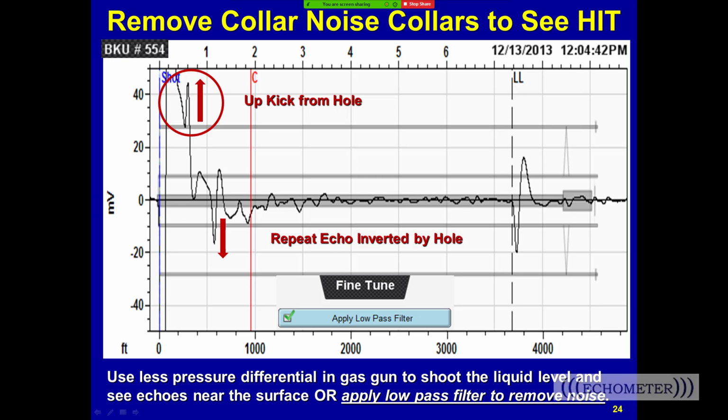Normally, if a well has a packer, it's going to be a gas well or a gas lift well or a well that has some kind of leak. And so when you shut the well in, if the well is a gas well, then the gas pressure typically increases. And if there's no standing valve in the tubing, it pushes all the liquid out. And this fluid level will be down in the perforations. And so a lot of wells that you shoot down the tubing, if there's no obstruction in the tubing and no standing valve, then typically there's going to be a lot of gas production, and not always, but typically. And the fluid level will be very accurate, and the pressure is going to be accurate, and it'd be a good test.